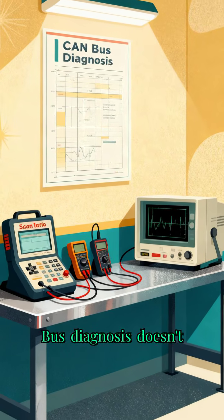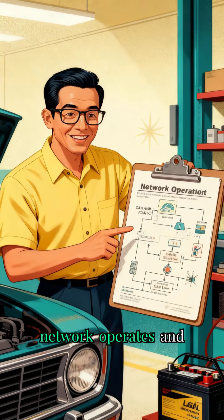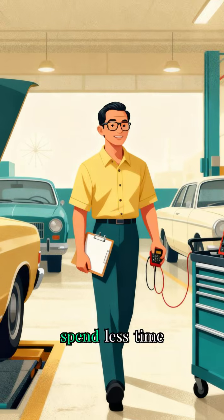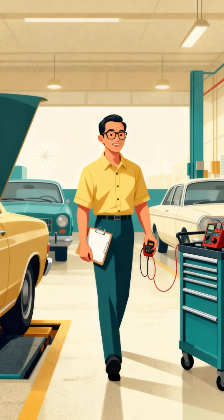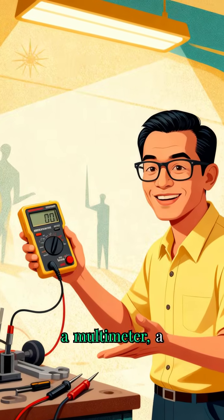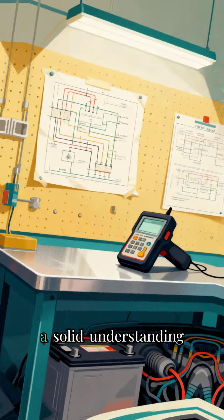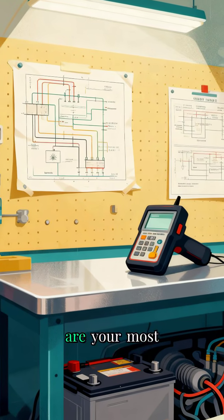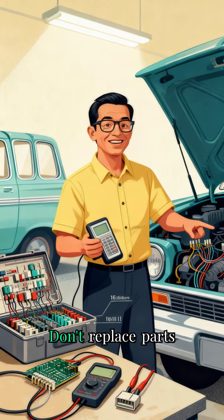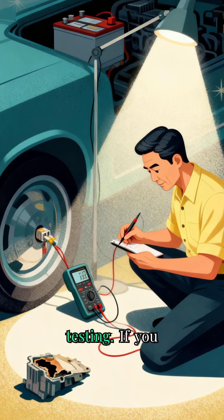CAN bus diagnosis doesn't have to be complicated. When you understand how the network operates and follow a logical diagnostic process, you'll spend less time guessing and more time finding the root cause. Remember, a multimeter, a wiring diagram, a scan tool, and a solid understanding of the system are your most valuable diagnostic tools. Don't replace parts until you've confirmed the fault through testing.